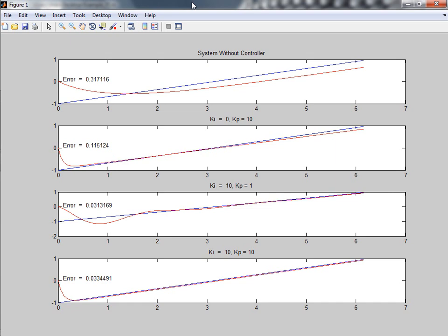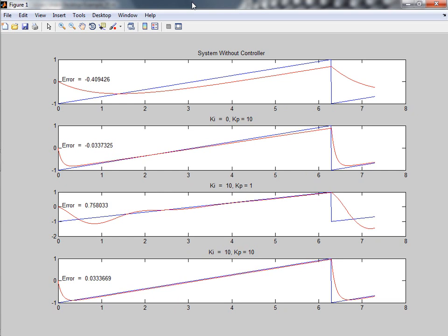I don't know. It was much faster than this one. But saying to improve both the steady state error and dynamic response, so reducing rise time, kind of the rise time. But overshoot will be increased.